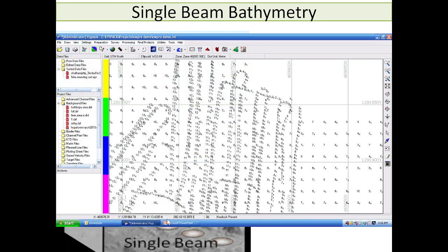And the depth data is acquired something like this. So here, using HYPACK software, we could show this demo data carried out by CWPRS in Khadakwasla. So the boat traveled path, you can say 2.6 meter, 3.3 meter, 4.1 meter, 4.6. So these are all the data which we use in our satellite-derived bathymetry for training my network to predict the other depths. So this is the boat traveled path. These are all the gridded data which is used in the software for analysis. Here you see this is equally spaced data.